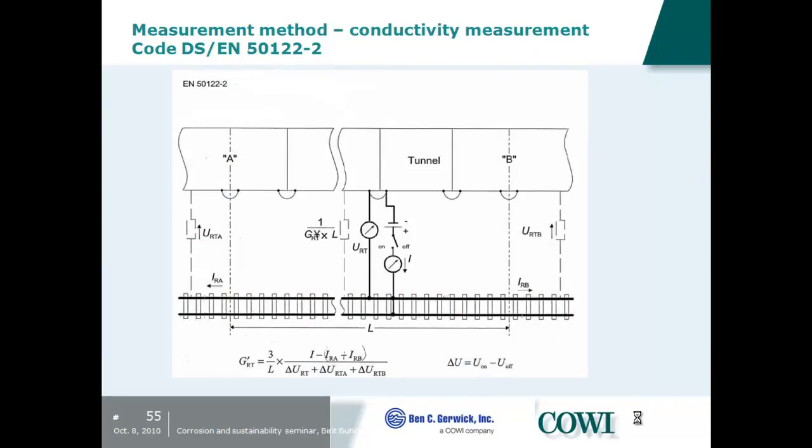We did measurements on the conductivity following one of the European codes on this, where we can measure if there's a certain leak to the tunnel structures next to these rails.